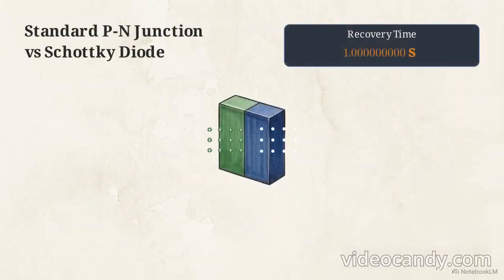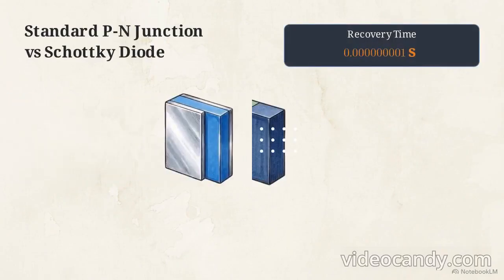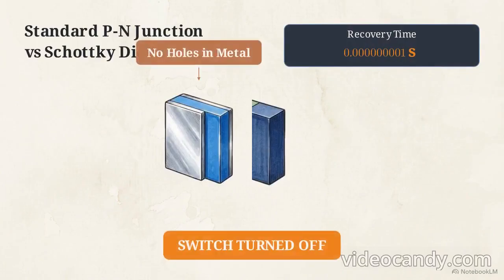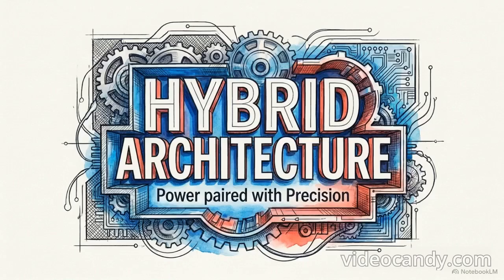The Schottky diode replaces the entire P-type semiconductor with an aluminum-silicon metal junction connected directly to the N-type material. This removes the slow recovery time associated with holes, driving turn-off speeds down to the nanosecond range. By modifying the internal geometry of the semiconductor, engineers trade raw voltage capacity for switching speed. This geometrical balancing act led to the IGBT, the insulated gate bipolar transistor.